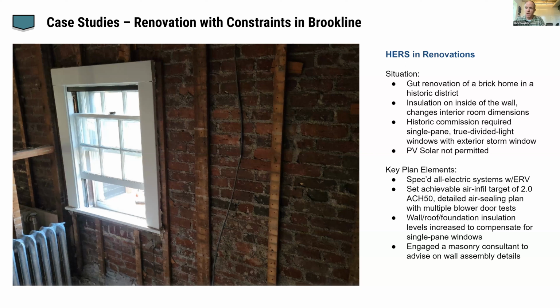The wall, roof, and foundation insulation, we increased to compensate for the energy loss of the single pane windows. And then because it's an old brick home and we're changing the thermal properties and the drying potential of the wall, we engaged a masonry consultant to advise on the wall assembly details.